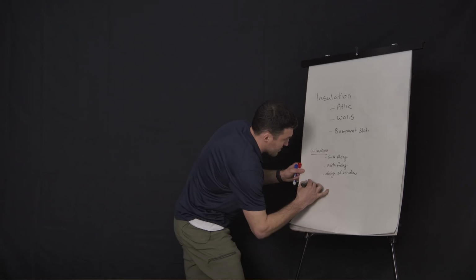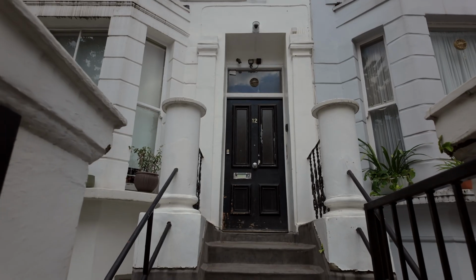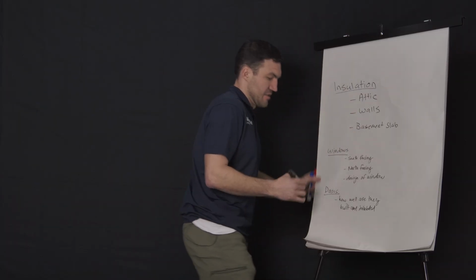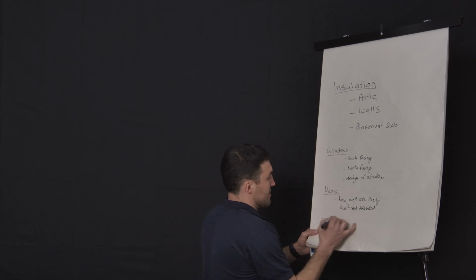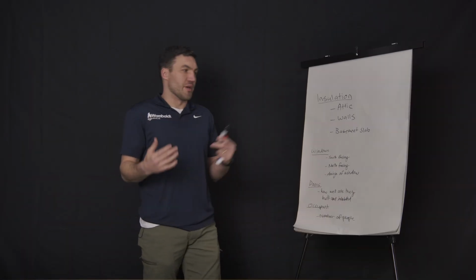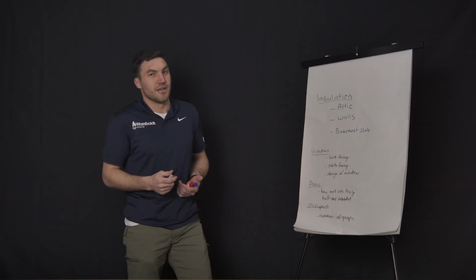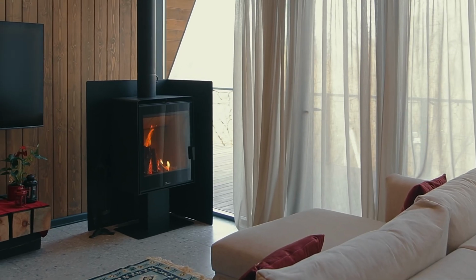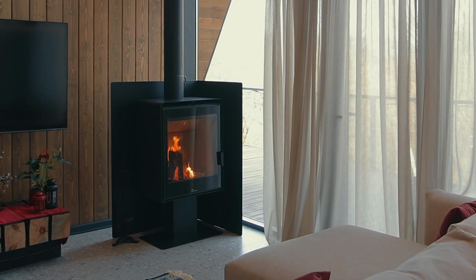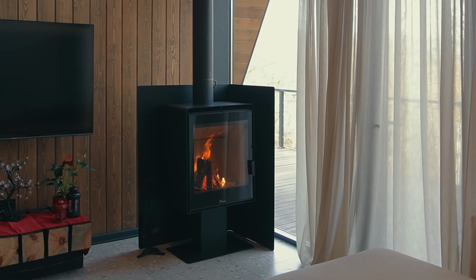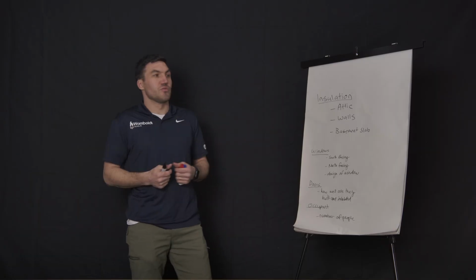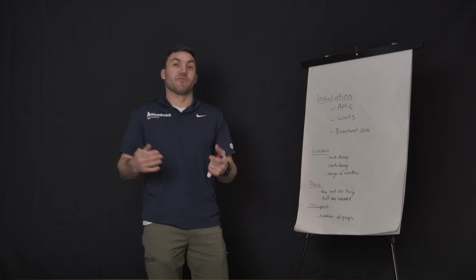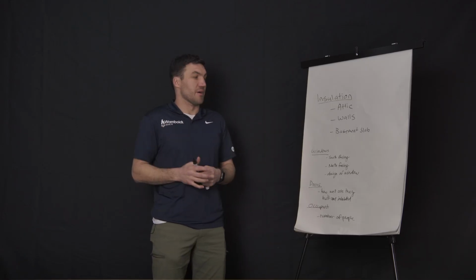We look at the doors, how well are they built and insulated, and we also look at how many people are in the house. So occupants. Now these are just some key factors going into what we look at when we do a design. We could also look at how many electronics you have. Do you have an older fireplace, a newer fireplace? Is it sealed? Is it not sealed? Again, this is just brief to show you what actually goes into sizing your house when it comes to looking for the proper furnace for your house or the proper air conditioner.